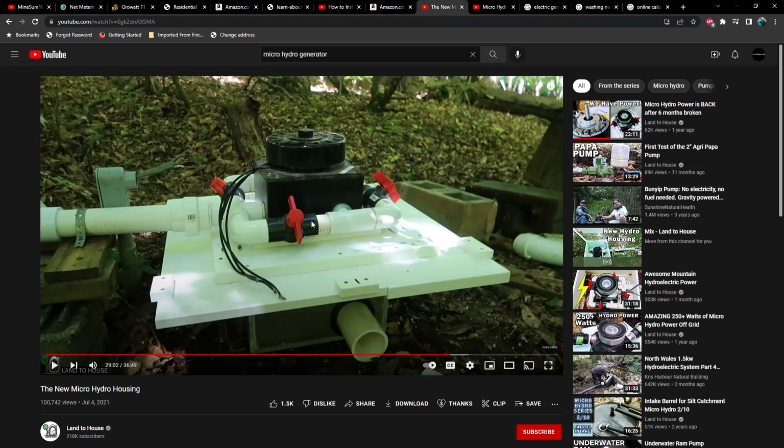This particular unit produces, I think, a maximum of about 500 to 550 watts continuous, and continuous meaning 24 hours a day. With a solar system, you're going to get about 6 hours a day, maybe 7 or 8 during the summer, but on average maybe about 6 hours of usable sunlight. Let's say if you've got 6,000 watts at 6 hours, you've got 36 kilowatt hours. Something like this, you'd get about 12 kilowatt hours out of it a day, but it also costs